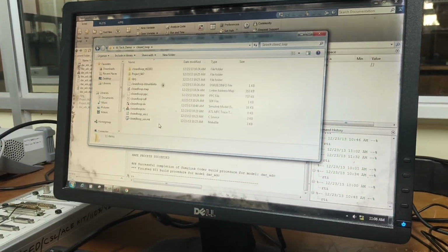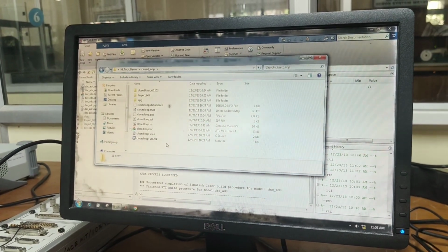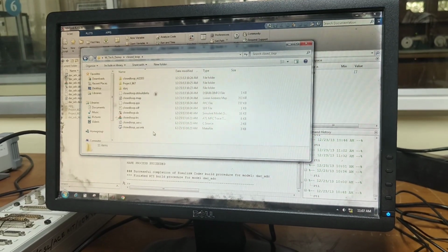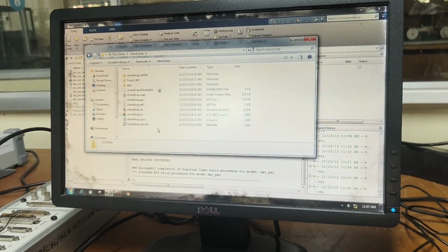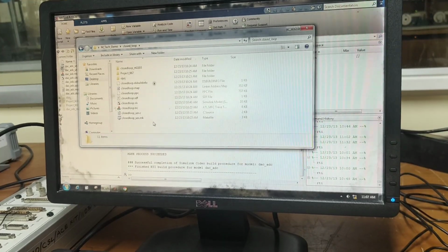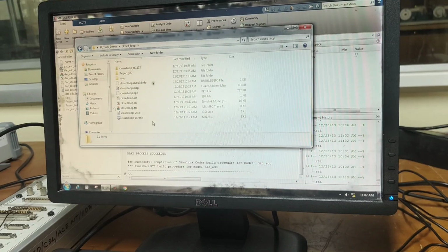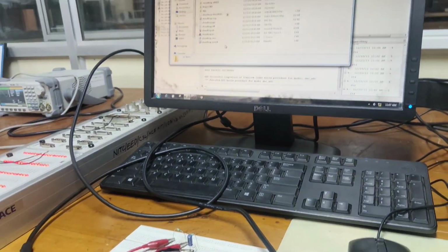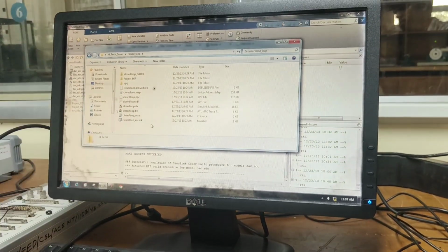We go for the closed loop diagram. In dSPACE, the general practice is that the real system, that is the hardware, is present in the real world. The plant to be controlled is present in the real world, and the controller we design in MATLAB, Simulink or ControlDesk and check the system. But currently, in the first phase, we are doing the inverse of it. The lag compensator which we designed is in the hardware, and the plant to be controlled is in the PC.